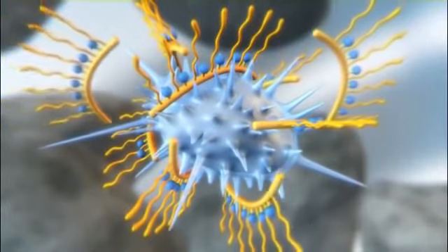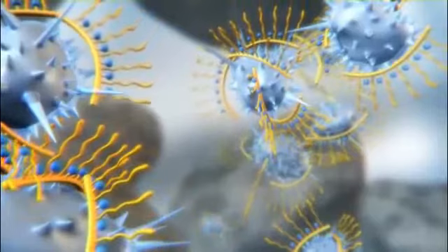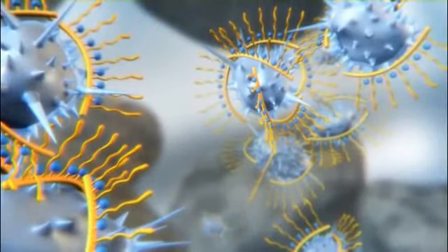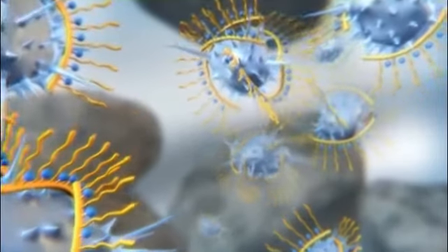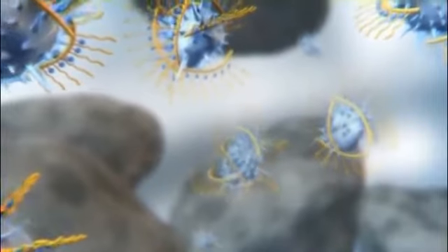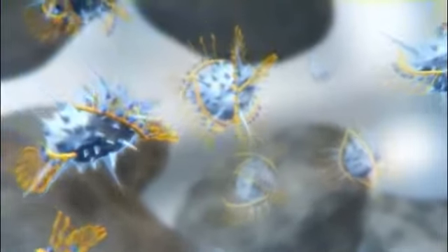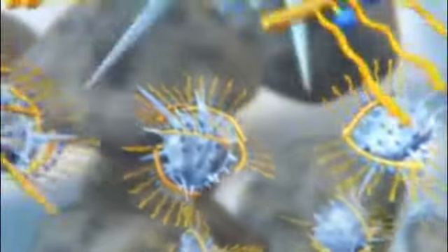When the PCE molecules are mixed with liquid concrete, they are absorbed onto the surfaces of the particles contained in the concrete. The side chains of the molecules point outwards, like the spines of a chestnut burr, and hold the particles at a distance to each other. This makes it easier for them to move against each other, and the concrete becomes more fluid. Concrete can be given the desired properties by varying the length of the main and side chains.